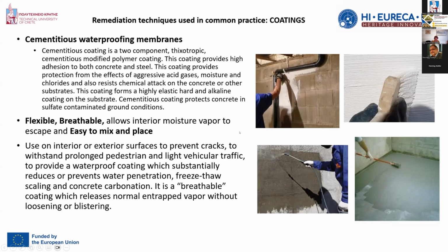And the concept of applying a breathable coating is important not only in the structures of historic significance, but even in the modern construction, because the most moisture that is entrapped inside the building could create a lot of deterioration effects and could initiate a series of reactions between salts and dissolving all the main compounds that the building is consisted of.